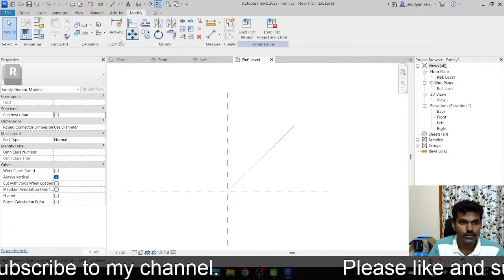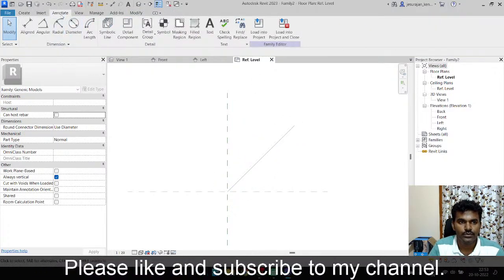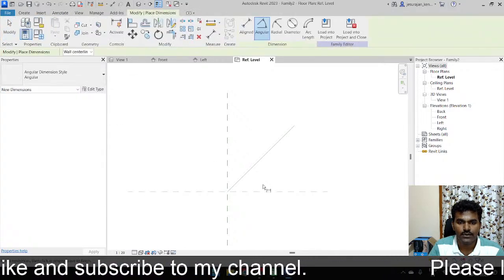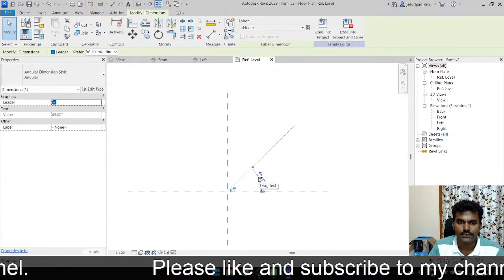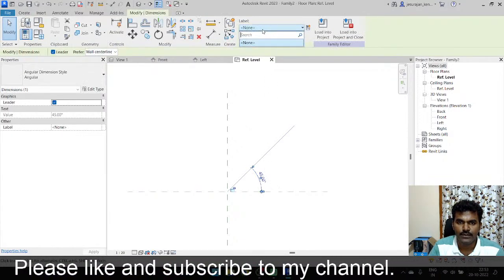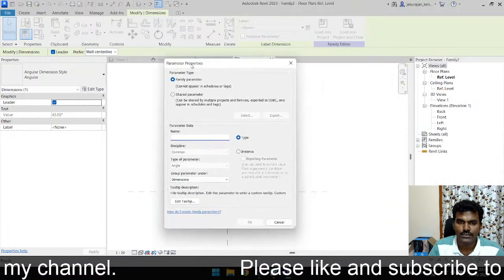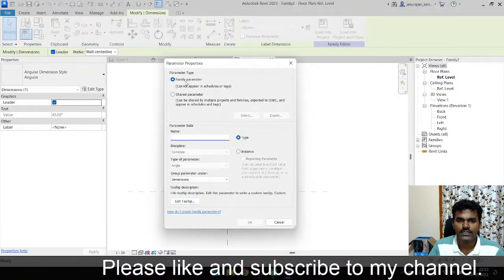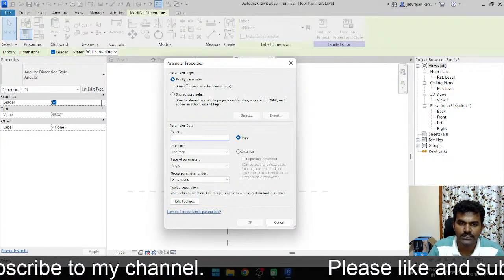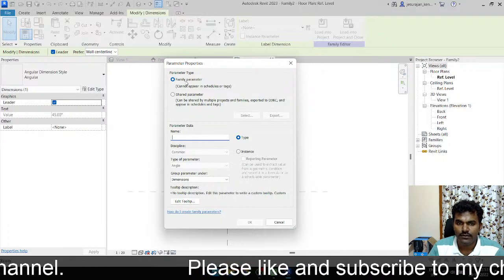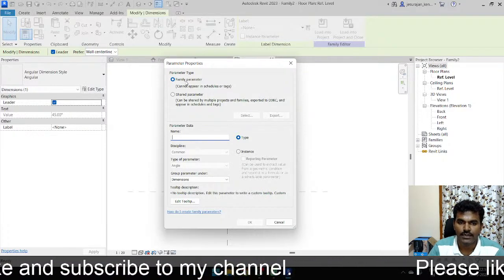Now we can give an angle dimension. Go to annotate, take angular, take this angle, and now make this parametric. In the parametric properties, I'm going to keep this as a family parameter because we are just generating a concept. Once we are okay with our family, then we can make that a shared parameter.